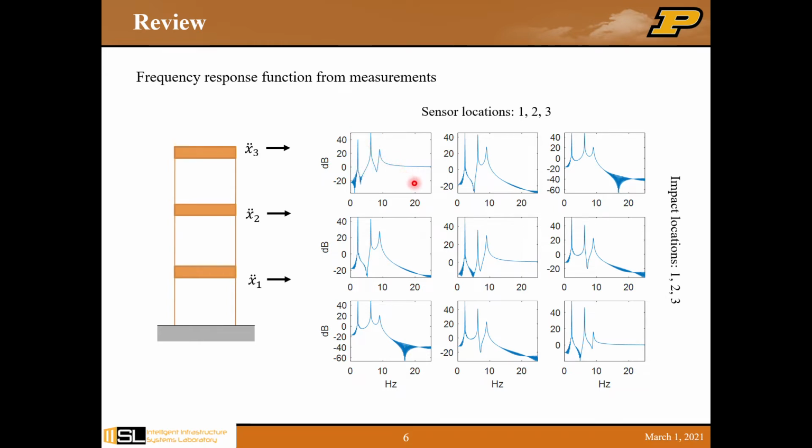And this is exactly what we discussed before, the driving point. So the driving point is the location where the force, the excitation, and the measurement are at the same location. Okay. And for that corresponding FRF, we will have the peaks representing the resonant frequencies. We also have zeros representing the anti-resonance frequencies between each pair of poles here.